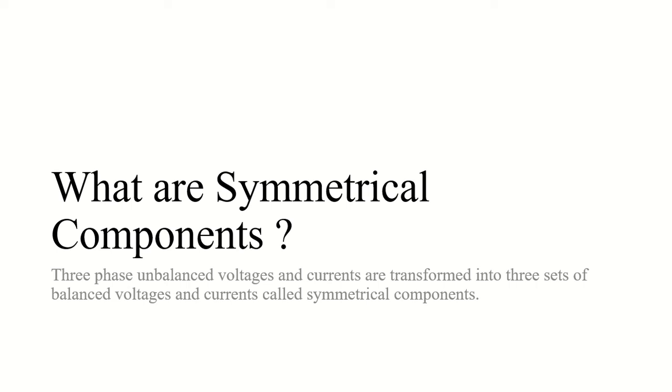By using this method we can resolve any problem related to an unbalanced system. We can resolve an unbalanced system of impedances into three equivalent single phase systems with independent values of impedances. The three independent impedance systems can be suitably connected to represent all types of fault conditions, not limited to any one particular, but we can use it for all types of fault conditions.